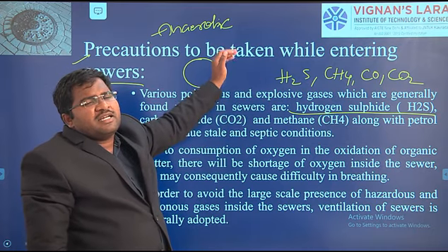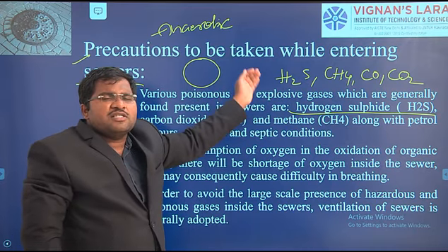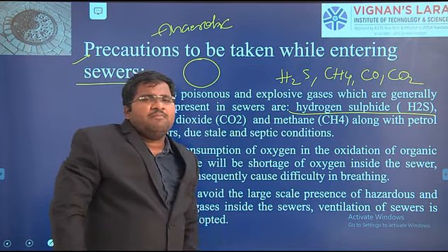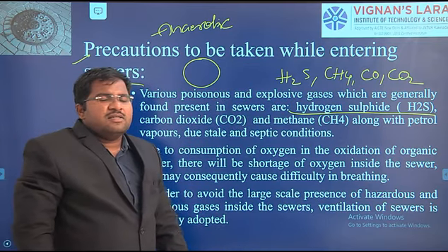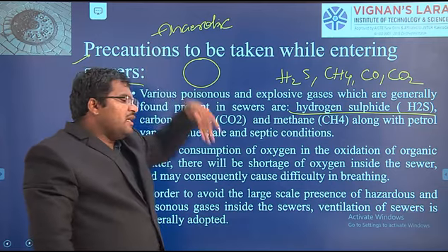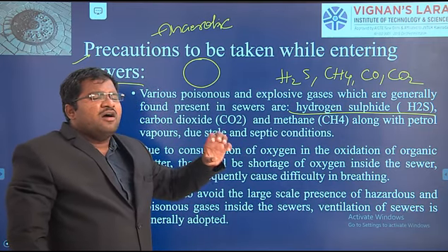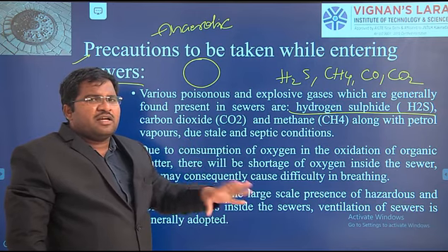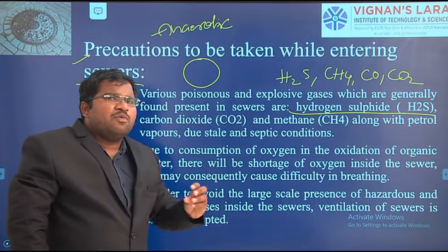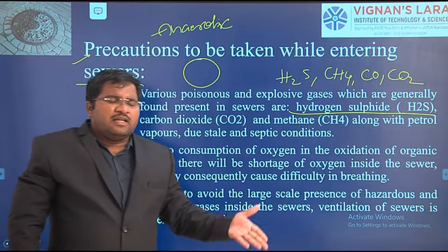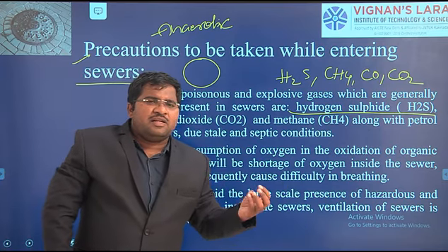Aerobic reactions will give us CO2 gas as the end product, but in the case of anaerobic reactions we are going to get H2S, methane, and carbon monoxide. These types of gases will be released since the sewers are closed, underground, and the wastewater carrying all the organic matter like food matter, fecal matter, everything will get decomposed. You will smell it.